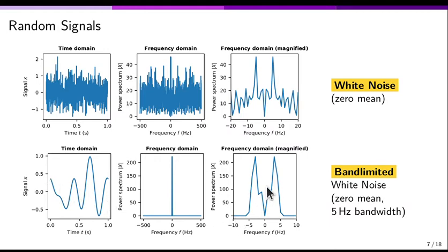What this means is that if you want to generate one of these random signals, you randomly generate this and then do the inverse Fourier transform, and you get this back out. This is something you will be doing in assignment 2. The fun, complicated thing in there is that in the Fourier domain, these are going to be complex numbers. So yes, you have to randomly generate complex numbers, and you have to make sure that the symmetry works out. Again, this is talked about in the assignment itself, and also in intro to signals and systems courses.